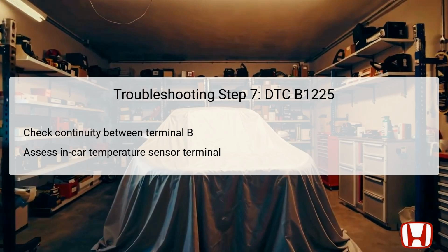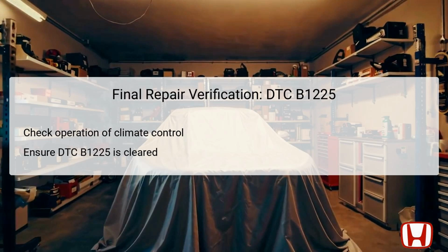Like before, the presence of continuity indicates that the wire is conducting properly and that the sensor should, theoretically, be working. Conversely, if continuity is not present, it implies another open in the circuit that needs to be fixed. This step is crucial for thorough circuit diagnostics, allowing for targeted repairs that can restore the climate control system to full functionality. Once all repairs have been performed related to DTC B1225, the final repair verification step is essential to